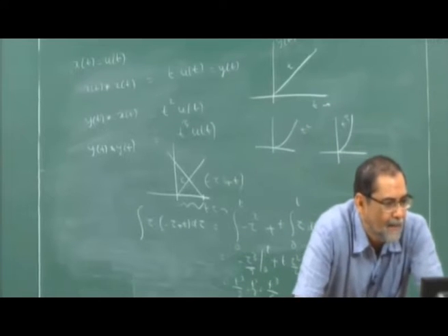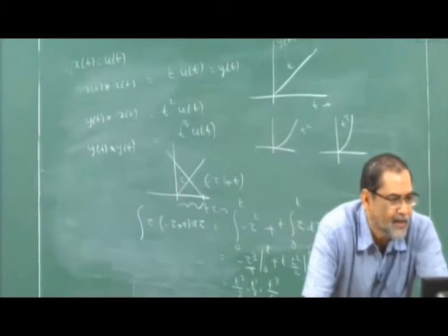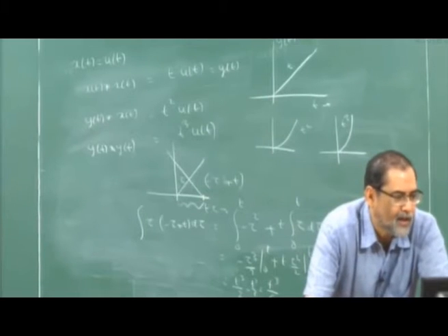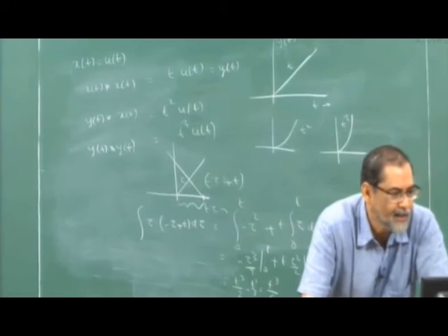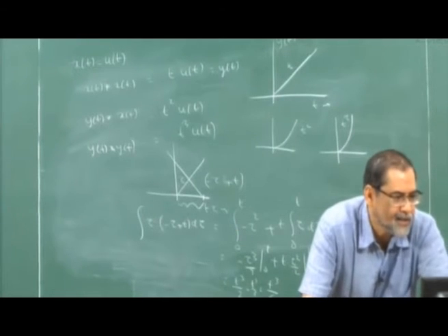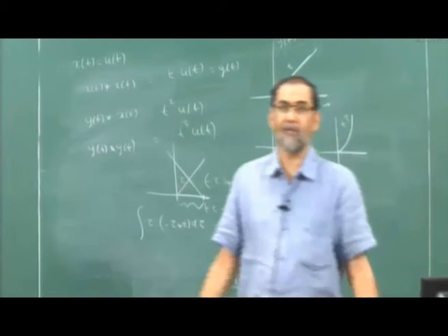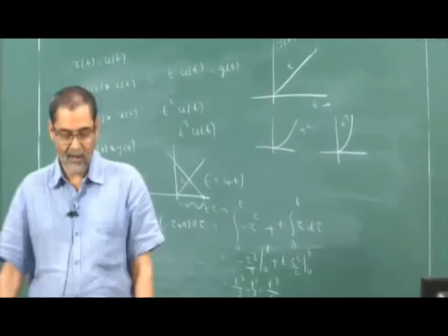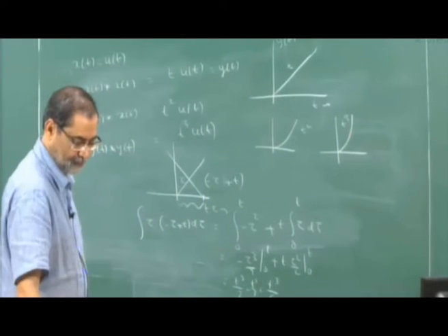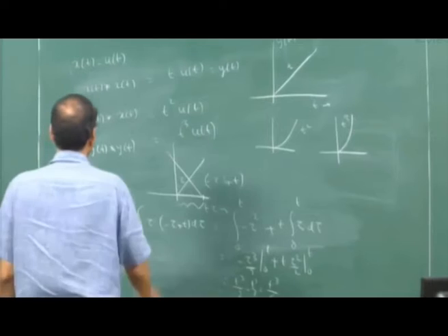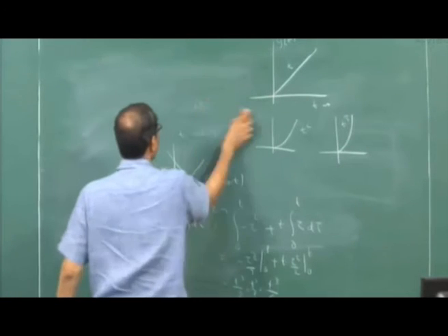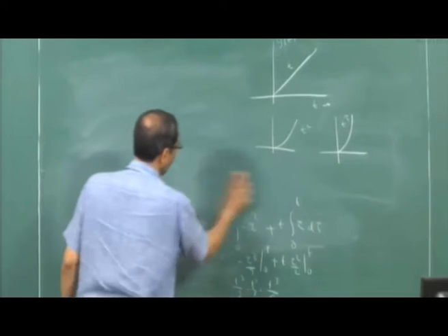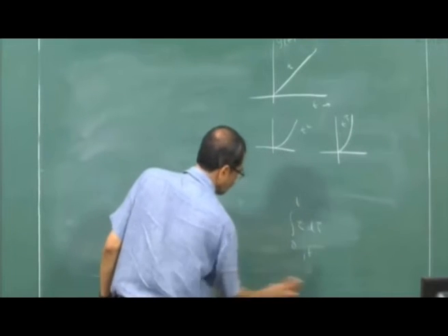Okay. Another question from PhD Tech. It says if H1(t) is a low pass filter and H2 is a high pass filter, they are in tandem connection. Can their connection be interchanged? I mean, why not? If it's an LTI system, why not? As long as both are LTI systems, it doesn't matter at all. We could do one first and the other next.